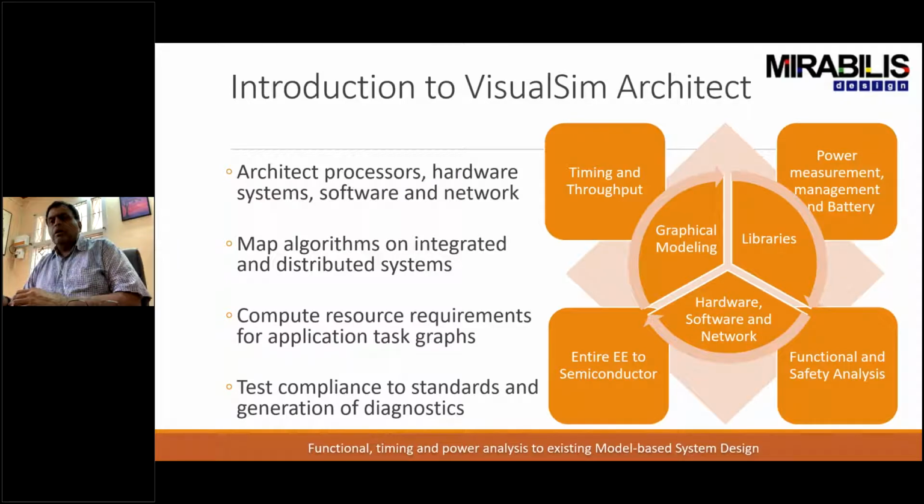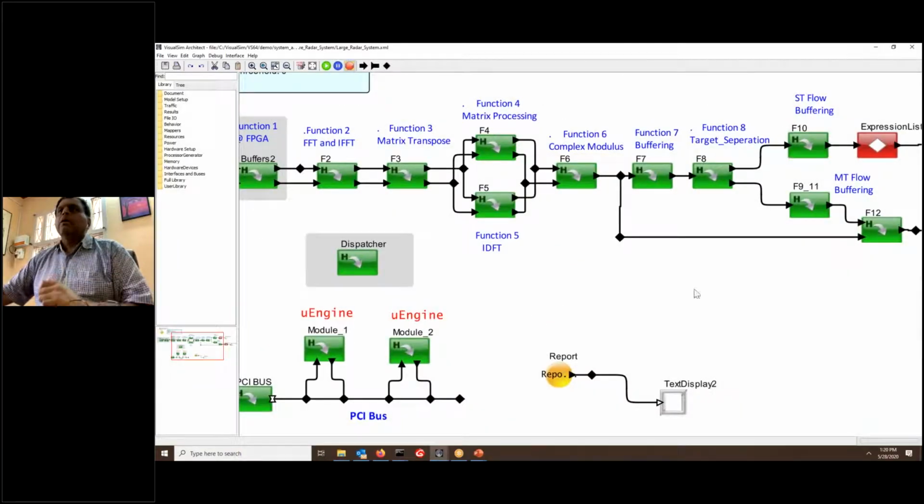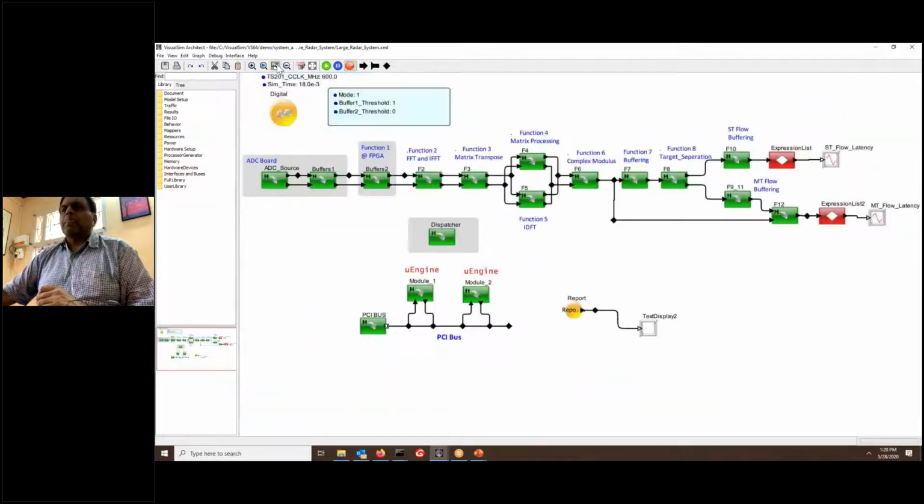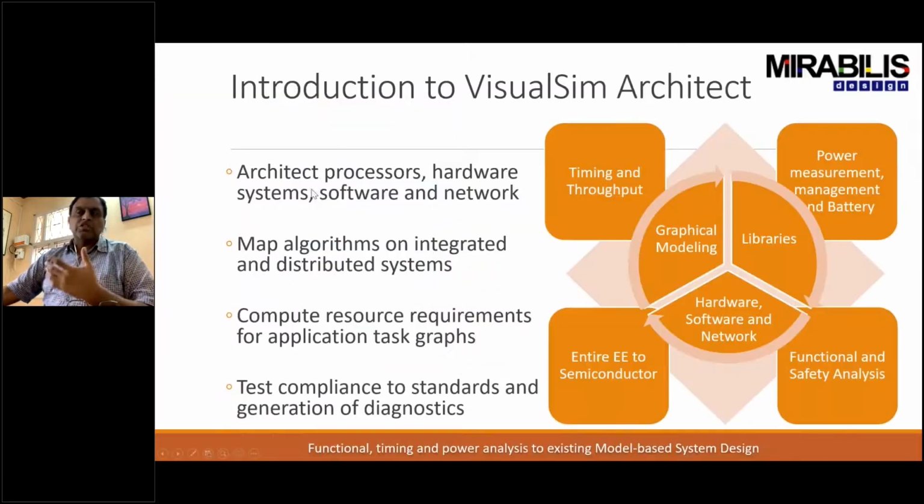So, for example, if you look at that earlier model, like this one here, you can see that's the sequence of application. But now some of these are in hardware. Actually, the first three is in hardware. Only then it starts getting more software. So you can see how I could maintain that information, also determine what's my resource requirements. How many DSPs, how many accelerators, things that are required.